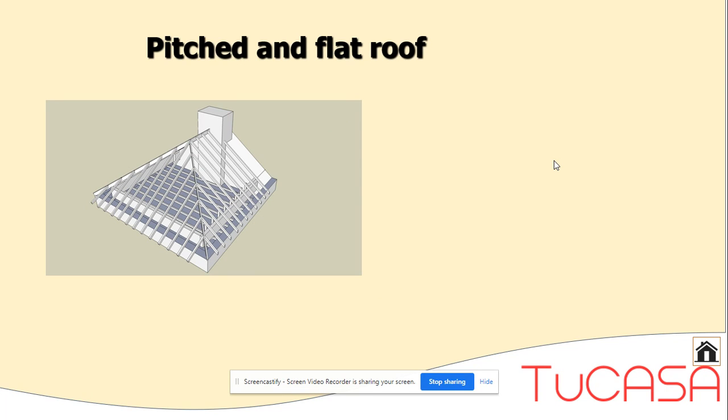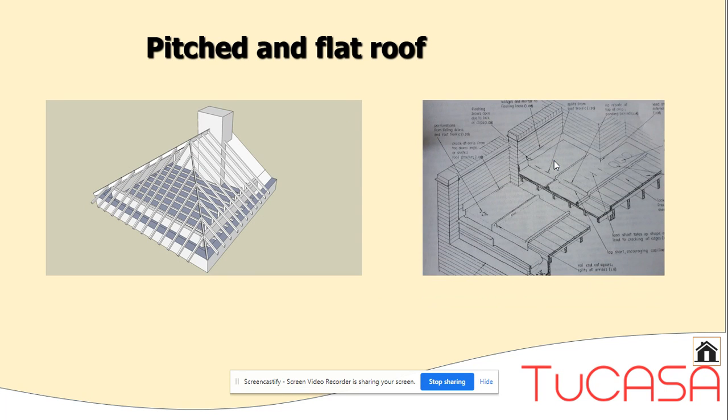Moving to roof level, where we may have pitched roofs and flat roofs. The different components of a roof. This is an older roof. Modern roofs tend to be formed in prefabricated timber trusses, which are prefabricated in the factory, but these older roofs were assembled on site with rafters and purlins. This member here supporting the rafters.